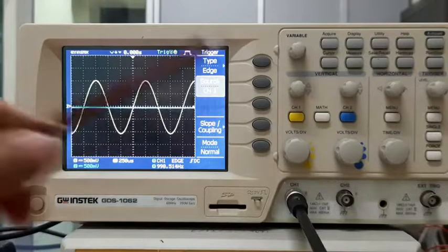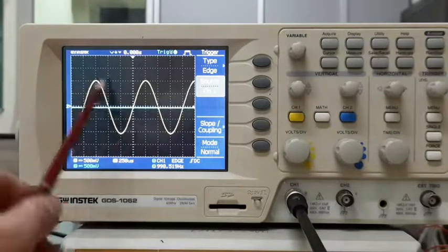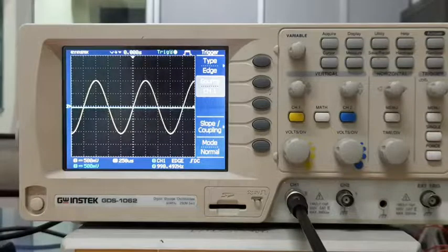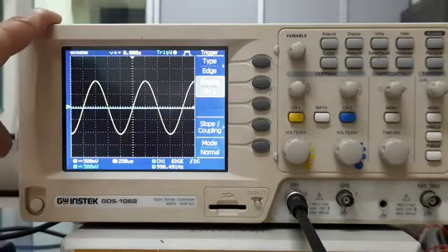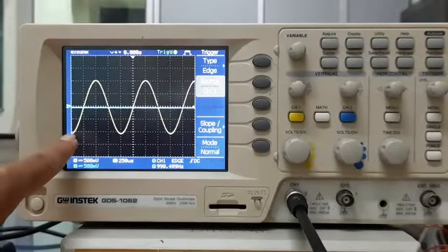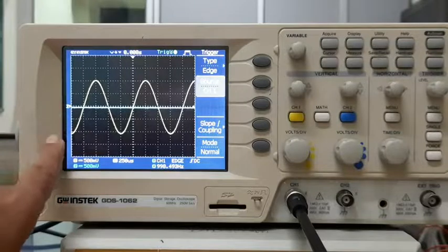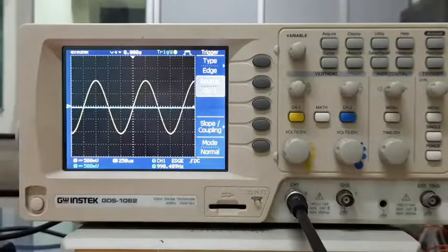And as soon as we have selected the source as channel 1, you can see that now we have a steady state waveform, right? It's not something that is frozen in time. It's because the input is basically 1 kilohertz sinusoidal waveform, and it's continuously going forward in time. However, the refresh rate of the oscilloscope now matches with the periodicity of the signal, right? So that means every time the same part or the same region of the waveform is displayed on the oscilloscope, and that's why we see it as a stable signal, right?